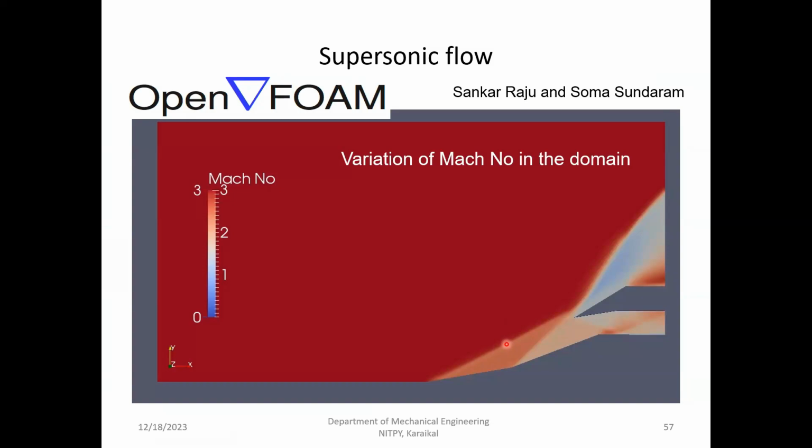Here, there will be a file called P. You have to go to that. And then in that file, there will be a line setting inlet. Then in that, you must specify whether it's going to be a Dirichlet boundary condition or a Neumann boundary condition. If it's going to be, then you go to another file and give the value of pressure there. So that's how it's more of a coding kind of thing.